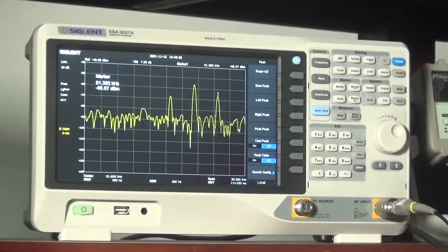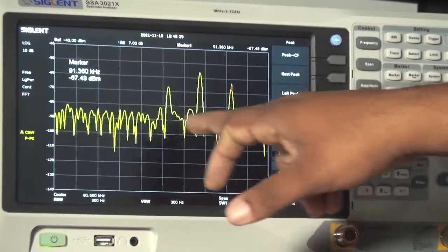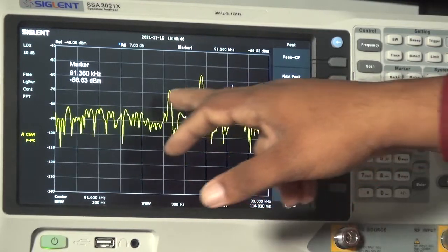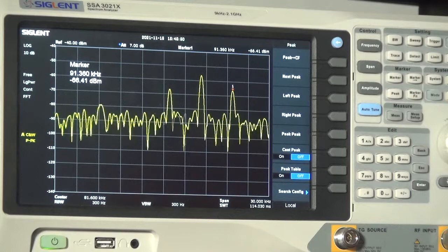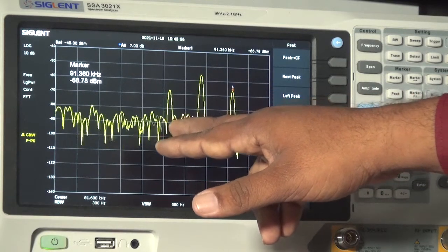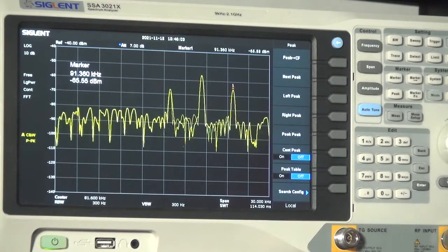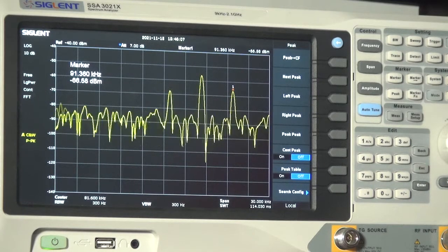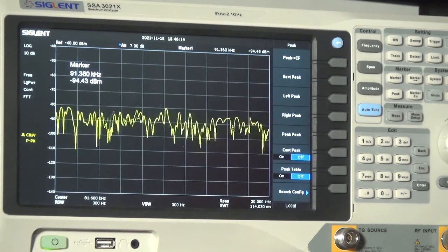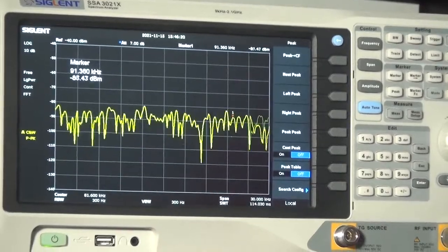So, you can see one carrier peak and two side bands. This is our carrier signal and these are our side bands, which are created from our message signal. So, this should be Fc minus Fm, this should be Fc plus Fm, and this is Fc. So, the spectrum is okay. One modulator is okay, and the other modulator will also give us the same result.